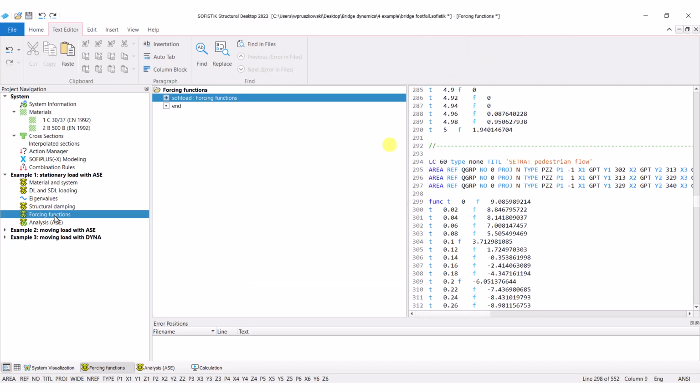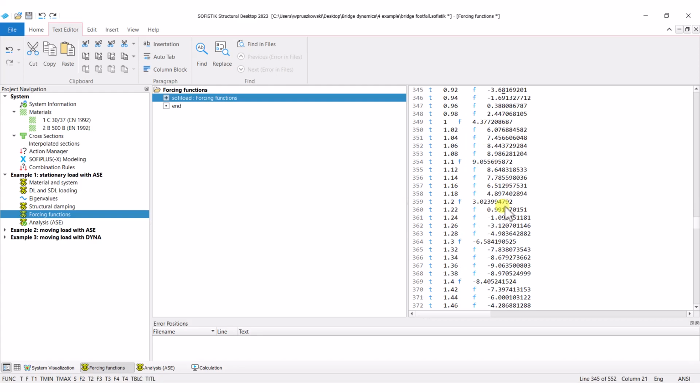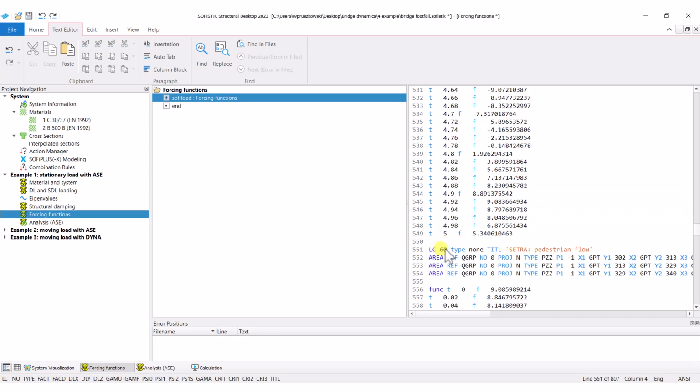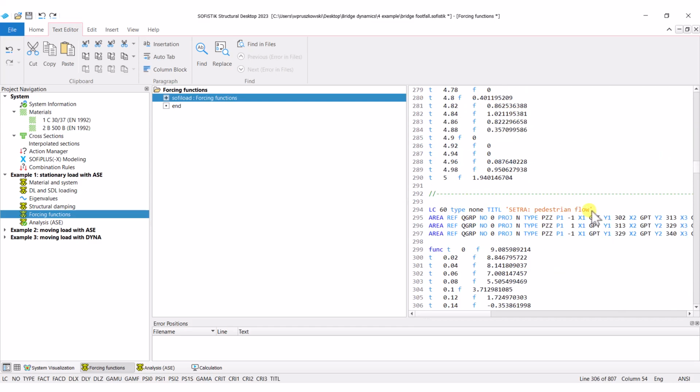Let's try to change the loading frequency without changing the loading magnitude, and let's try to compare the results. In order to do so, let's copy load case number 60 and let's redevelop it with a different number for a different frequency. So copy and paste. Let's change this number to 61 and let's note a change in the frequency to 2.5 Hz. And let's add this small description to the original one for clarity.